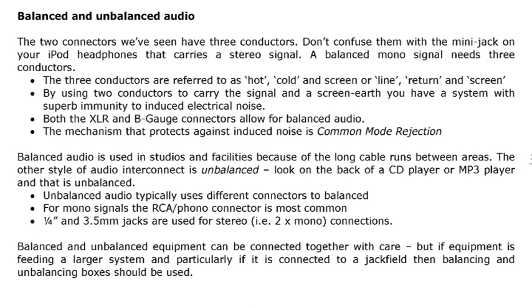And in fact, it's not just audio signals that use balanced systems, common mode rejection to get rid of noise. You find balanced signals relying on common mode rejection everywhere. Serial control going to your PC, network cabling, everywhere you find balanced signals, because it's a very, very good way of getting rid of electrically induced noise for no extra money, for no extra processing or anything like that.